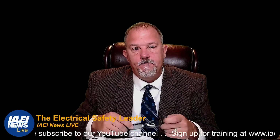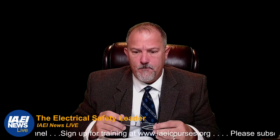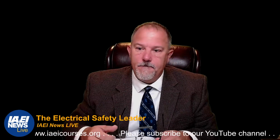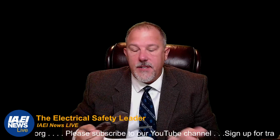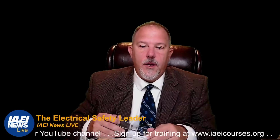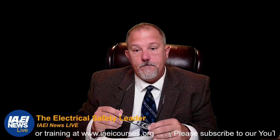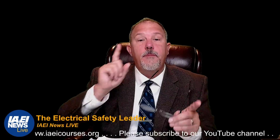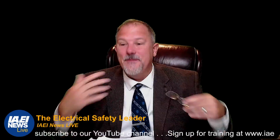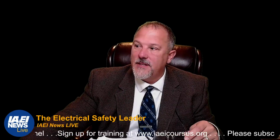All right. If it's a small conductor, you're probably using 6, 9, or 12-inch rung spaces, I would say. Type TC, if you're looking at small diameter cables like your TC cable, PLTC, ITC. But in any case, you're going to think about the wire that's going to go in that cable tray to help you determine your spacings. And be mindful too that on some of the cables, if you put too large of a span, I mean, this stuff is, I'm going to say common sense. I'm never going to use that word either. What I think is common sense might not be common sense to someone else.